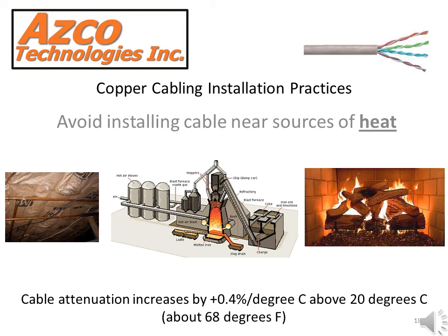Avoid installing cables near sources of heat, whether that's hot water pipes, fireplaces, furnaces, or any kind of forced air heating system. Attenuation can be created by any type of fluctuation in temperature on that cable. Keep that in mind when installing your cables.